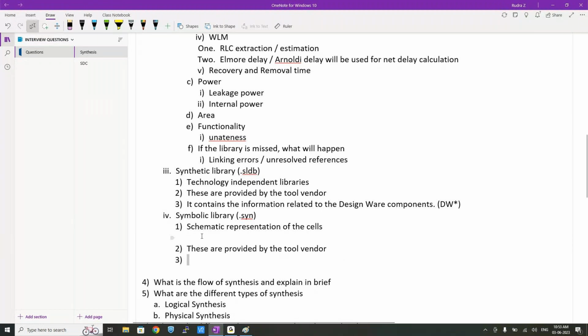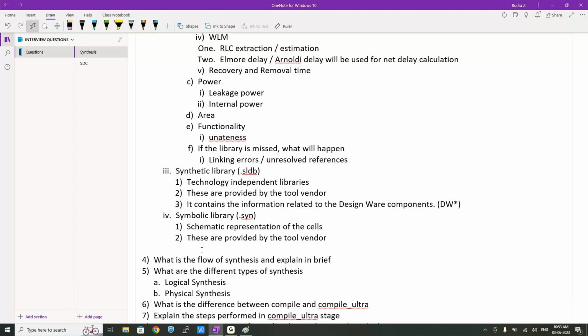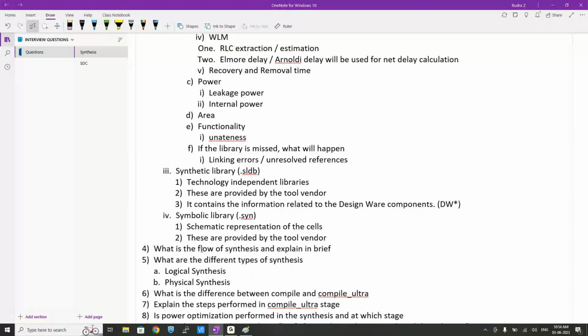Clear for everyone so far? Normally, these libraries will be provided by the characterization team, right? Yes, correct, the standard cell team, we can say. If you want to add any new gates, those new gates have to be appended to the equivalent variables of the symbolic library.